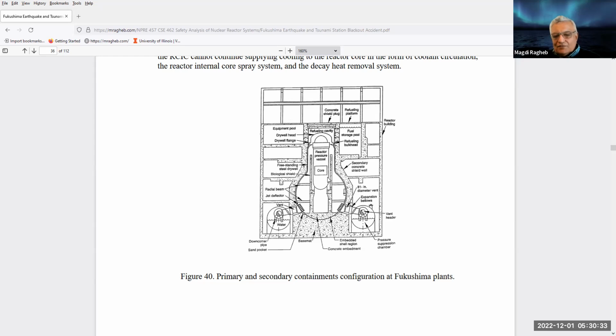How could that steam explosion have happened? That area under the core of a boiling water reactor has the inlet for the control rods. They come in from the bottom. Why? For two reasons. We have drying equipment at the top of the pressure vessel in the boiling water reactor. There is no room there, like in a PWR, to insert the control rods from the top. And second, the boiling creates more bubbles or void near the top of the reactor.